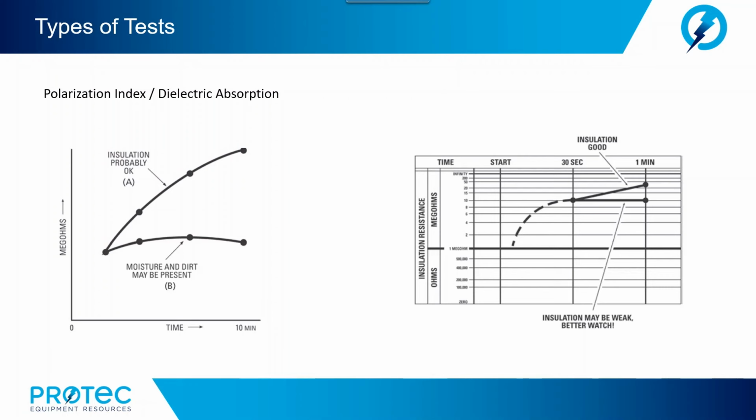Its value as a diagnostic indicator is based on two opposing factors. The current dies away as the structure reaches its final orientation, while leakage, promoted by deterioration, passes a comparatively large constant current. The net result is that with good insulation, leakage current is relatively small, and resistance rises dramatically as charging goes to completion. This changing resistance is exactly what an experienced technician wants to see.